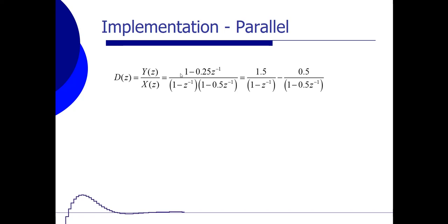All right, you're back. So you've done the partial fraction decomposition, and we have two parallel branches, two system blocks over here, which can be implemented in a parallel way. So we are going to make this system block, we're going to make that system block, and then we subtract that system block from this system block. So then we have, in this case, two parallel branches.